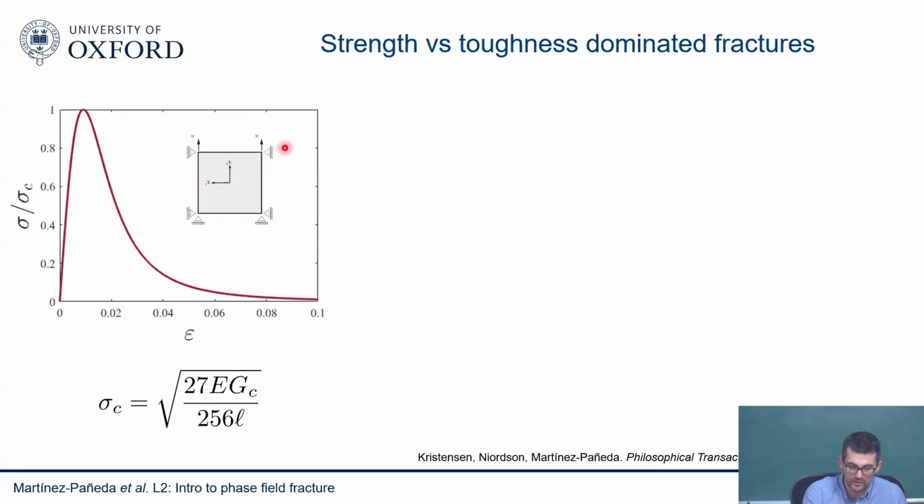Okay, so there's one aspect. At this point, this is a perfect question, because someone could say, you said the advantage of this method versus non-local continuum damage mechanics is not that different. It's much better than other computational fracture mechanics methods like XFEM and so on. But the main advantage is this connection with the physics. I don't have 8 parameters to feed that I don't know where they come from. It's just the fracture toughness.